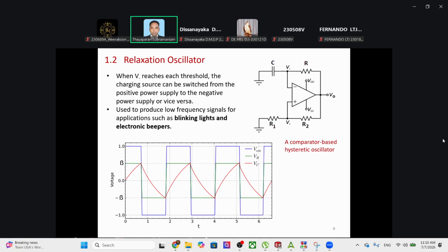We have a footer switch and a header switch. Header switch means close to the VDD, footer switch means close to the VSS. We call it power gating. The power is given to the VDD, VSS power is there, but power to the op-amp, to this circuit, is given only when it is needed.